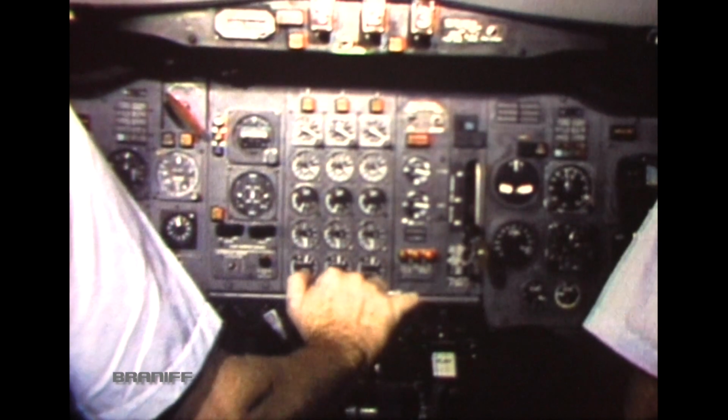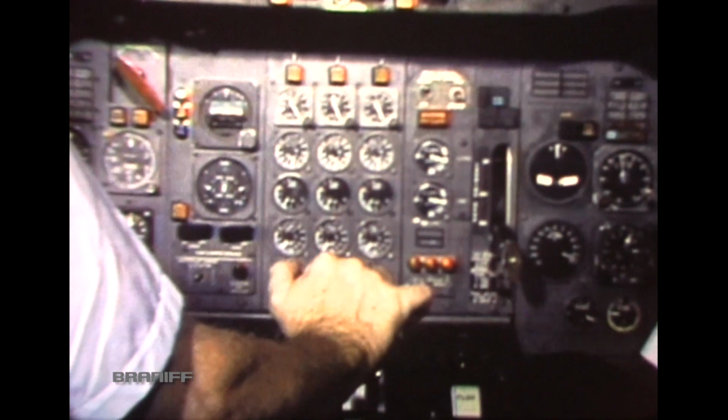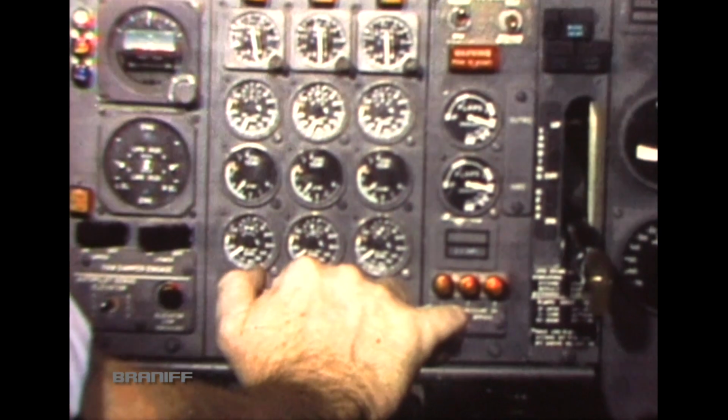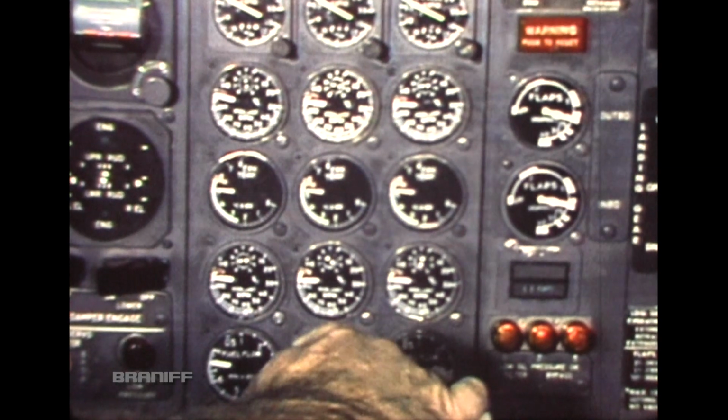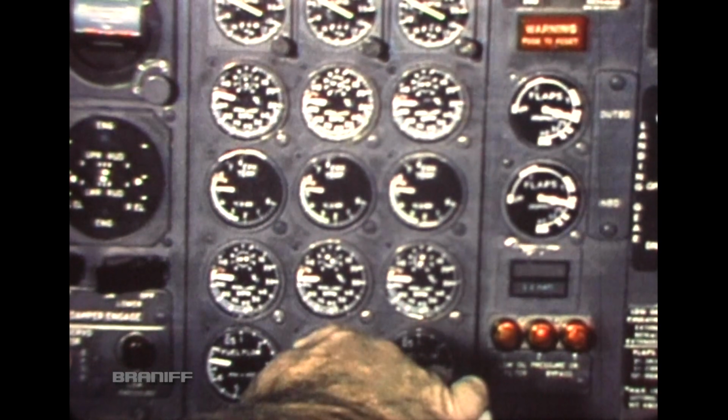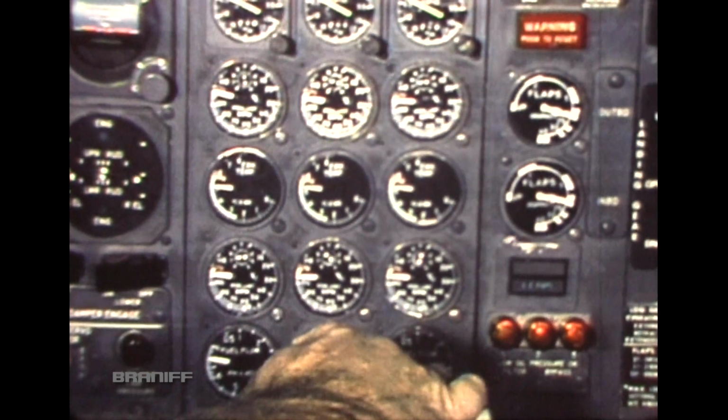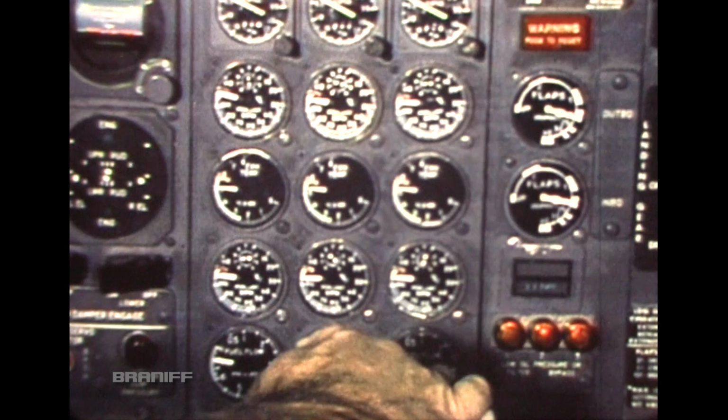Takeoff from a snow or ice-covered runway should be made using normal procedures with a few slight modifications. Start the takeoff roll with smooth, even application of thrust. Differential thrust is normally not required for directional control. Use full-rated takeoff thrust. Reduced thrust takeoffs based on the assumed temperature method are prohibited. Monitor engine parameters for abnormal indications. For example, cross-checking EPR versus N1 can provide clues to erroneous indications caused by a blocked PT2 probe.